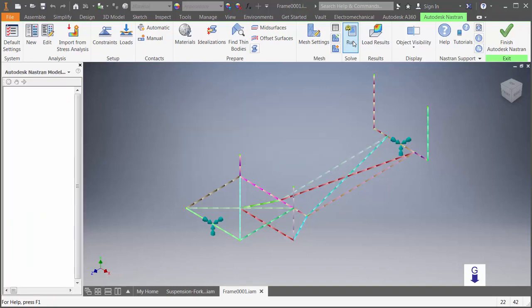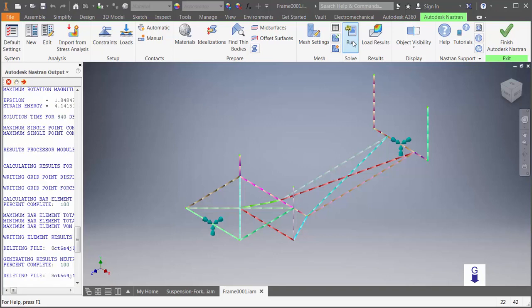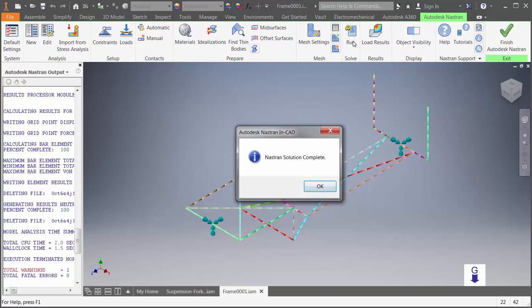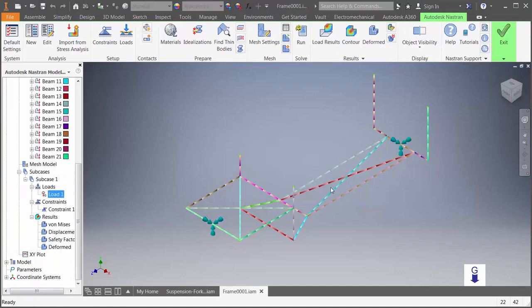First, you'll see that the mesh is automatically created if the model wasn't meshed first. Next, we changed it so that the in-CAD analysis files are stored in a subdirectory to help keep things a little bit better organized. We'll also now be able to tell if the results being imported are for the correct model and warn accordingly. If you've ever imported the wrong results and saw a big spike ball, you'll know exactly what I'm talking about.